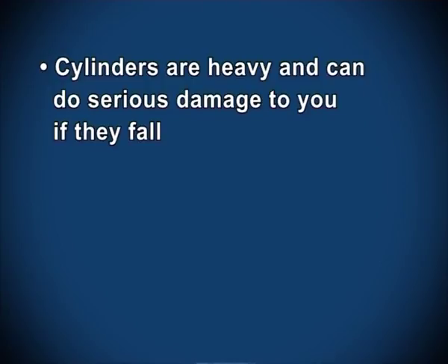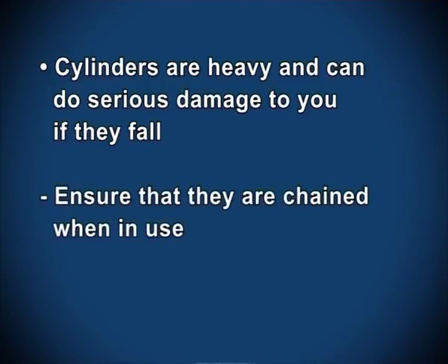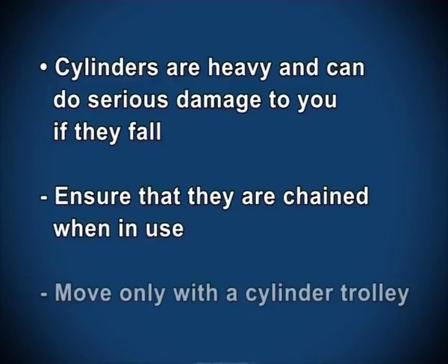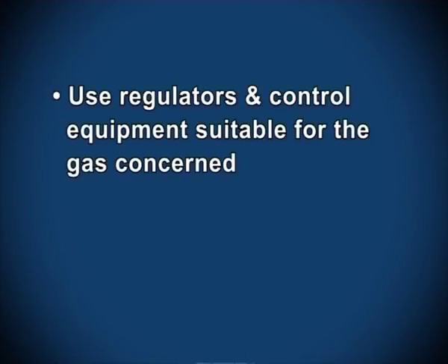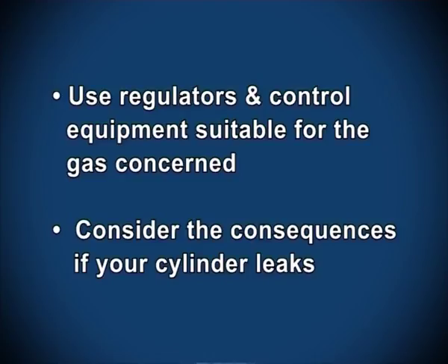Ensure that they are chained when in use. Move only with a cylinder trolley. Use regulators and control equipment suitable for the gas concerned. Consider the consequences if your cylinder leaks.